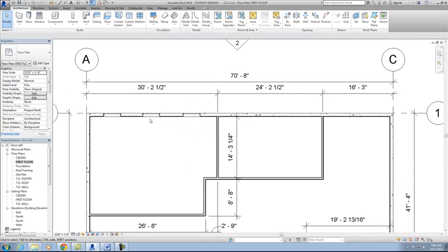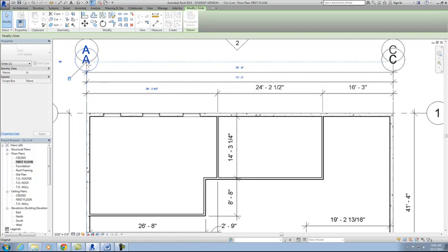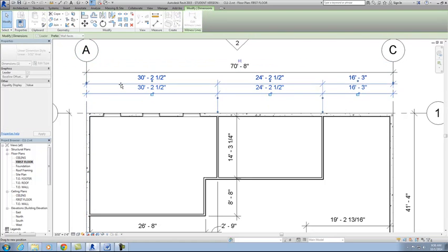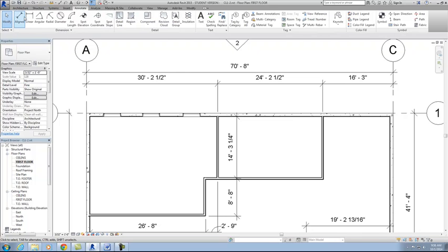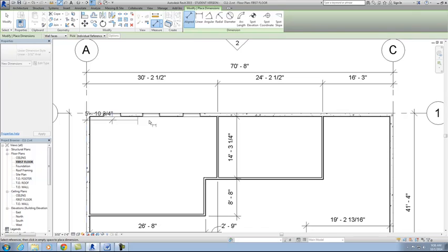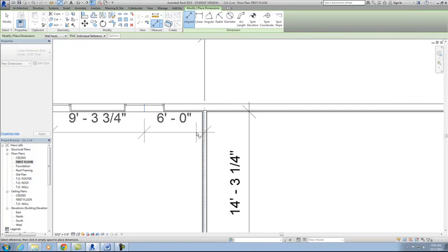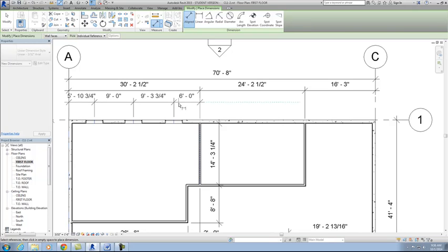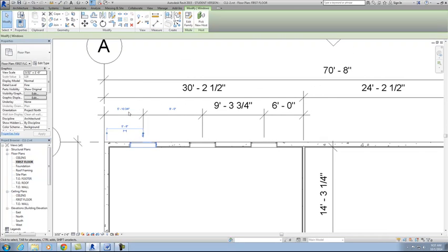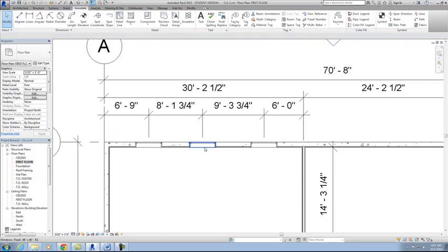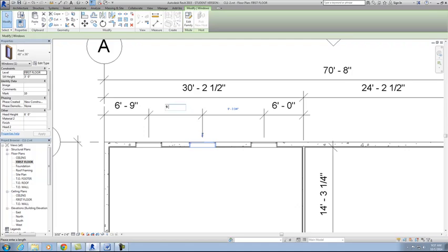And then you can refer to the portfolio for this, but I'm going to go ahead and add in a 3rd row of dimensioning here. This way I can still locate the wall locations, and then I'll do my 3rd row where it shows everything. So I'll go to Annotate, Aligned, and I'll go ahead and hit these first 3. There. Then I'll come back later and add more dimensioning. There. So now, of course, just like before, to move these windows to the correct location, I click on the window first, and then I'll type in the correct distance. (9.2).